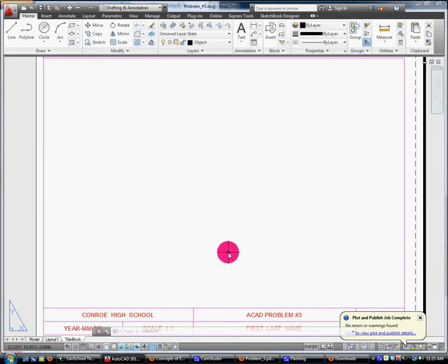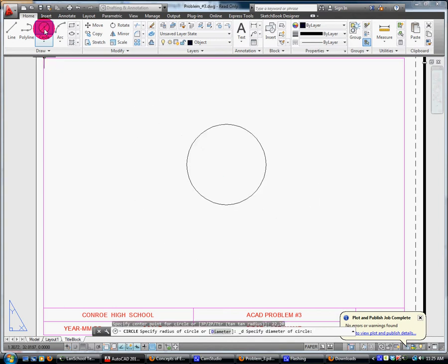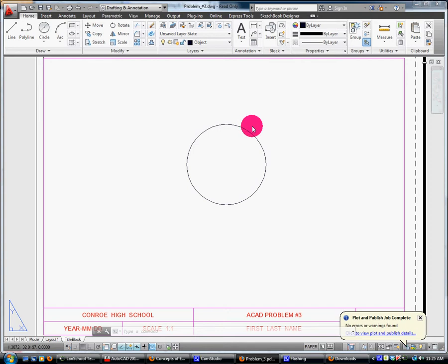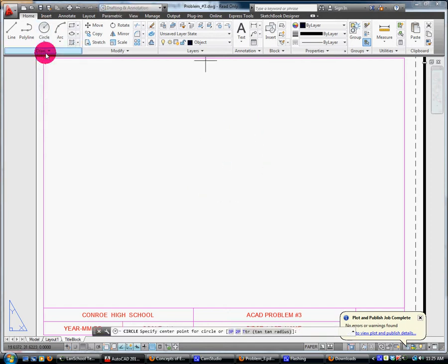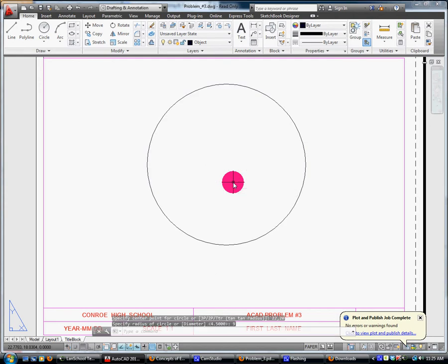Now, we're going to draw a circle that is 22, 20, 9. So I go to circle. Type in 22, 20, hit the enter key, type in 9, enter. There it is. Okay? That looks awfully small. Sorry, pardon me. It does not look right. Oh, it's because I'm still in the diameter. Make sure you're drawing a radius. 22, 20 is our starting point. Go back to our coordinate systems, and 9 is the size of our radius.